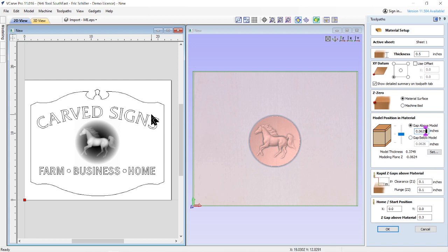We can do whatever. But what we want to do is make sure that this area is dropped just a tad. Because if you haven't set up the upper beam to be perfectly parallel to the material in this area, then you could have it flat spotting up at the top. If your upper beam is not perfectly parallel, you could have a problem. So this gives us a 1/16 of an inch of a wiggle that you won't see because we're just dropping this down 6 inches.